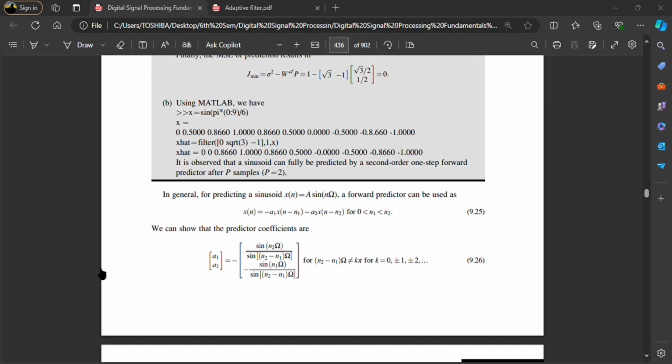Here you can see the block diagram of these adaptive filters, in which you can see the tap delay line FIR filter. If the filter has a tap delay, the finite impulse response structure, then the impulse response is equal to the filter coefficients. The output of the filter is given by the equation, where k refers to the time index.